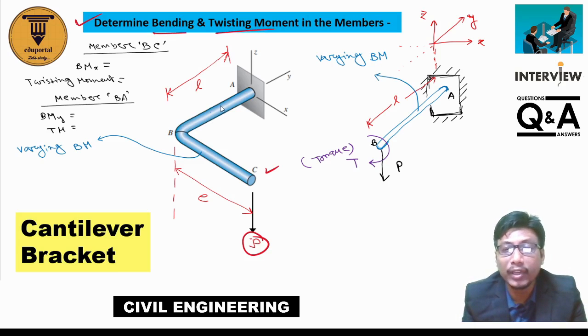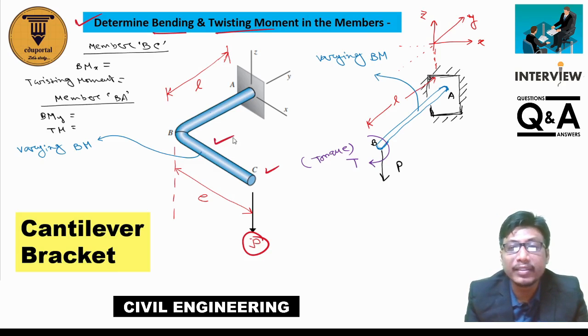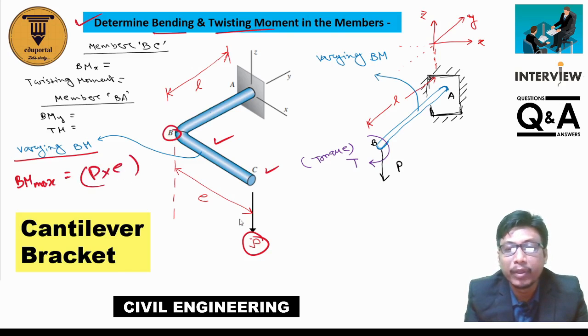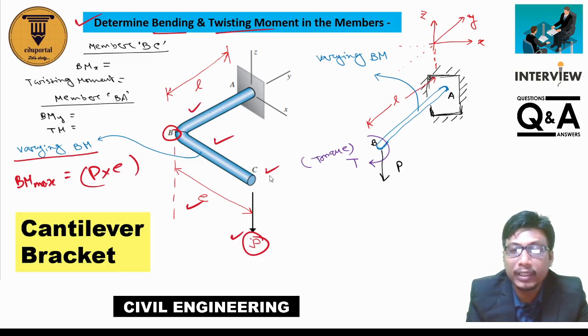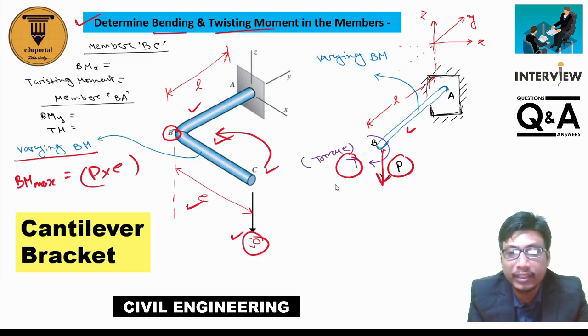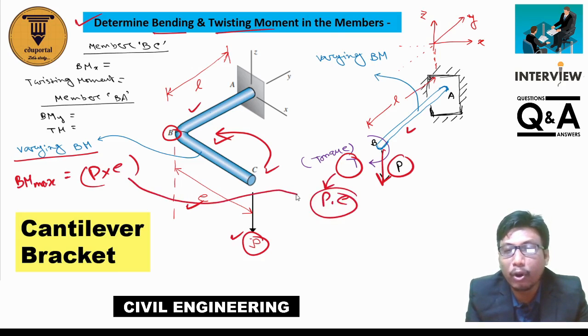Those who have already solved these kinds of questions know that in the member BC there will be a varying bending moment, and the maximum bending moment, BM max, will be at point B, and its value will be P into E. Now, for the analysis of member AB, we need to transfer this load from point C to point B. If we transfer this load, for member AB there will be a load P at this point, and along with that another load, T, the torque, which is equal to P into E. So the bending moment for member CB acts as the torque for member AB.